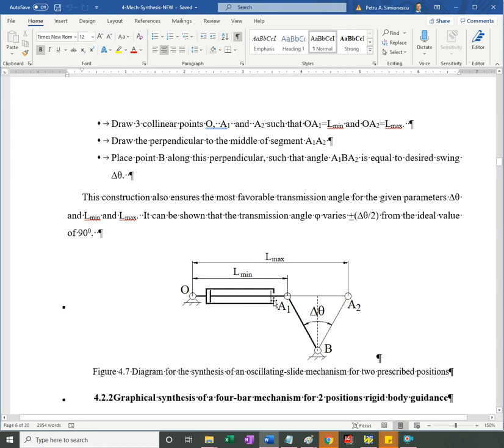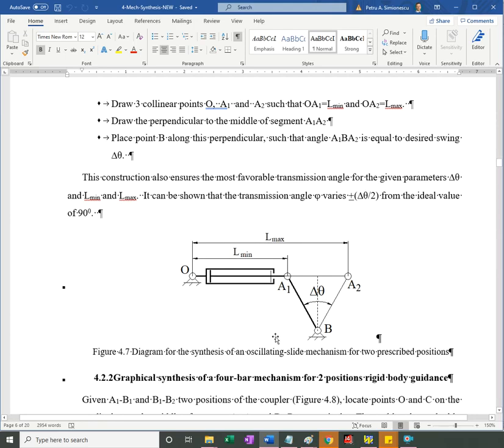It could be pneumatic actuator or linear actuator that is electrically driven. So I have L min, L max. You start with hydraulic cylinder, and you want to get an angle of swing, say 80 degrees. And L min is some number of inches. L max, it will be bigger, the swing or delta S of the actuator comes from the difference between the two.